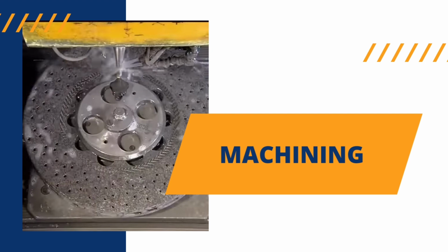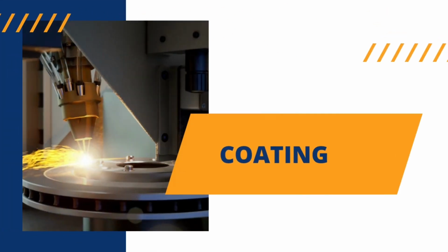Grinding operations with diamond tools achieve the desired dimension. The small lateral vent holes in the rotor faces are produced with an ultrasonic drilling process. The fifth step is coating. A coating is applied to all surfaces of the CCM brake rotor to provide oxidation protection.